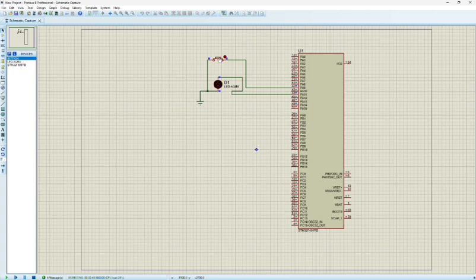This illustrates the principle of digital signal interfacing, a fundamental concept used in embedded and IoT systems. Through this experiment, I learned how to configure and use GPIO pins in STM32Cube IDE, understand input-output data flow, simulate hardware behavior using Proteus, and test embedded code without needing a physical setup initially.